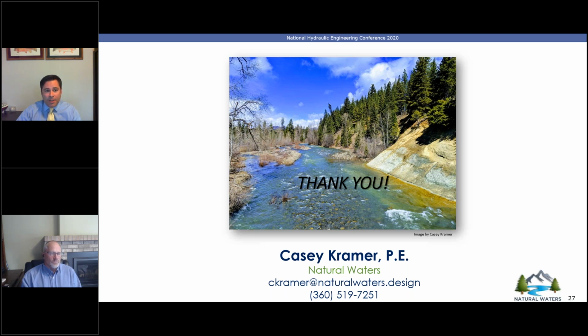Similarly, working with the Bureau to get their bathymetric data, we did something similar. That was taken a while ago, but instead of doing a full bathy topo, they just took strategic locations to verify that the data was still good. Then they were able to focus their efforts on the vicinity of the bridge crossings. So even though we had a 4-mile long reach over 2 miles wide, the actual amount of survey data conducted by the DOT wasn't that much.